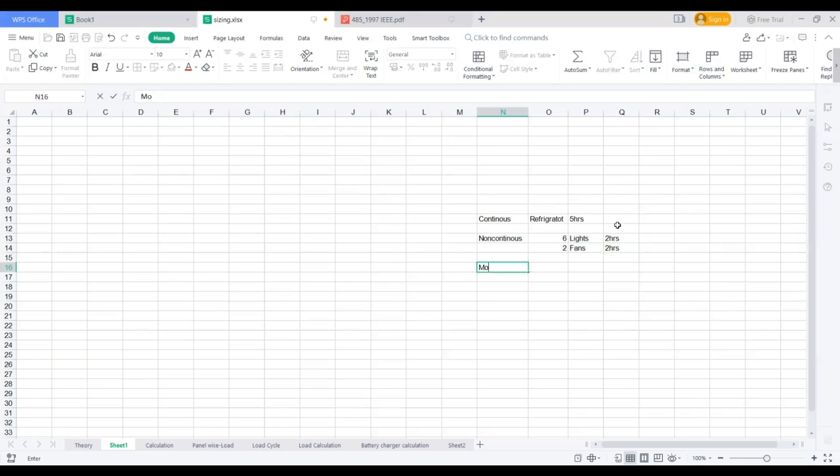And also momentary loads will be there. Generally, what would be the momentary loads? In the substation, suppose a fault occurred, the breaker opened, the breaker closed, or the isolator opened and closed. These are the momentary loads we can see in the substations. In a house, let's assume some loads are momentary, happening twice or thrice over the whole cycle of 5 hours. So I require a battery backup of 5 hours, or let's suppose for time being 3 hours.